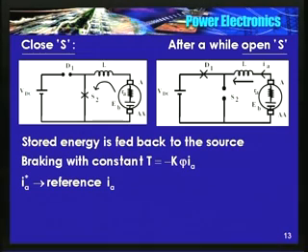It is Eb which is forcing the current through the inductor. If Eb falls, the rate of rise of current itself falls. Eb divided by L is the rate of increase in current. If Eb falls, di by dt when the current is increasing decreases. So the rate of increase comes down. But then what happens to the rate of decay?